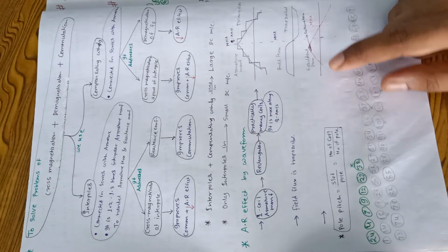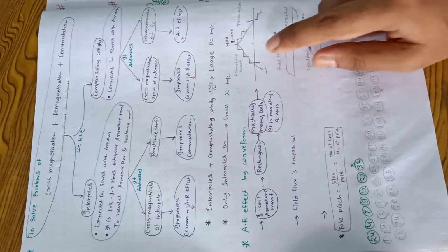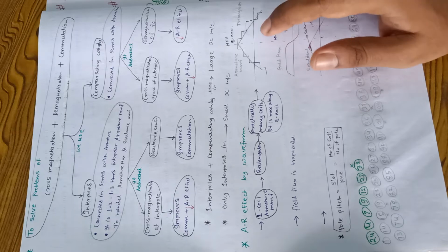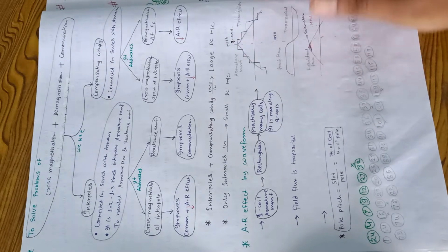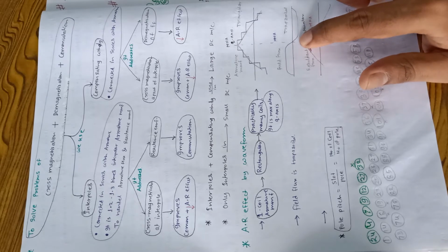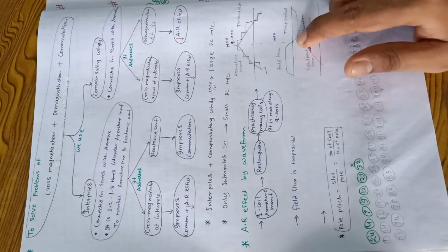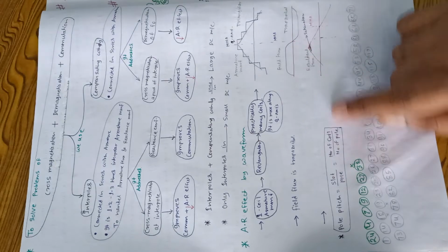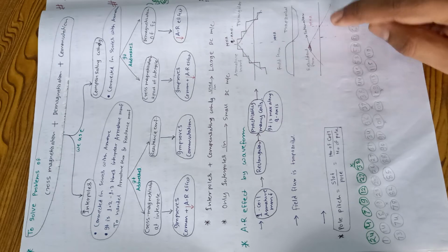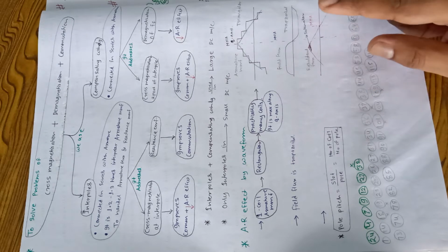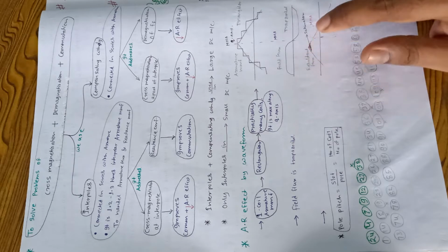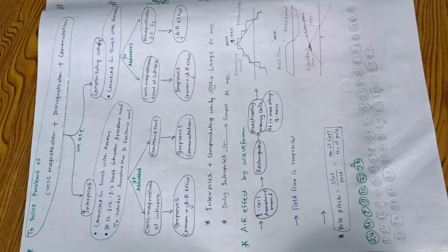So finally remember that armature flux is triangular in nature, and it peaks at the MNA and Q axis. Field flux is trapezoidal in nature, and it is zero at the Q axis and MNA. The resultant MMF is flat top triangular, and the induced EMF in the armature coil is trapezoidal AC.